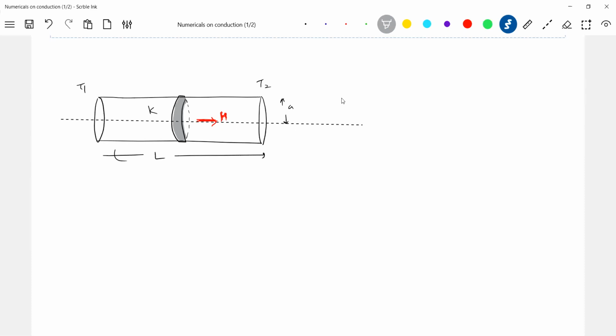So what is the thickness of this? Let it be dx. First we'll calculate the resistance of the small elemental disk. Let it be dR. How should we assume that elemental structure? The heat current, or the rate of flow of heat, or the thermal power, should be directed normal to the elemental structure. That is the method of assuming an elemental structure. Got that? Okay, what is the resistance of that elemental structure?